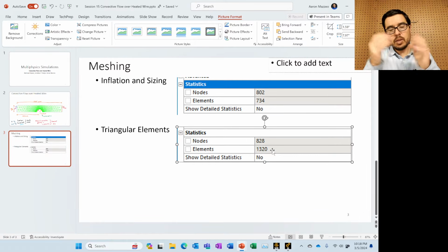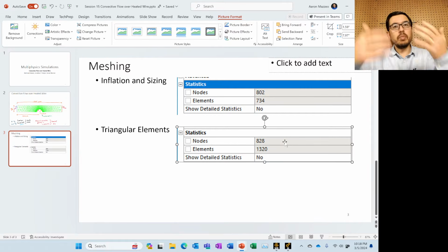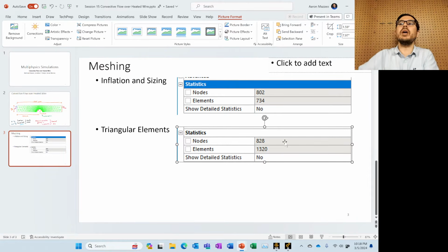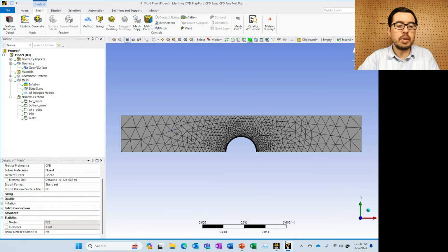As you decrease the length, you increase the number of nodes that you're going to have. So sometimes people will plot whatever interesting quantity they might have versus the number of elements, and as they've increased it to a certain number of elements and they see that the value is not changing, they'll say that they've got convergence.